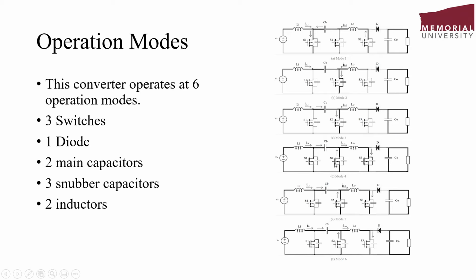And here, because of the output voltage, the direction of the current of the output inductor will change, and it starts to discharge the snubber capacitor.